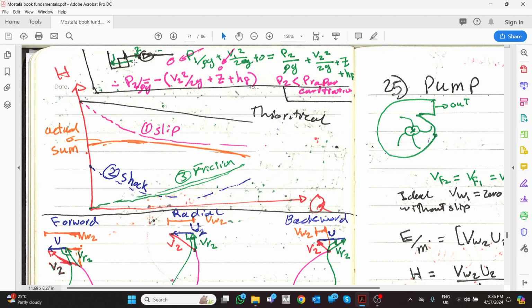So take the tank, Z is datum. So this is one. So this is equal plus H friction. Manipulate left and right. So you will get pressure 2 here, which is the pressure before the pump. So the pressure before the pump equals the velocity component, the kinetic component, the potential component plus the friction. Please ensure that this is the pressure if you multiply by rho g, this term. So ensure that pressure 2 is bigger than the vapor pressure, and if it is less than the vapor pressure, you will have a cavitation. This is a normal case about the cavitation.